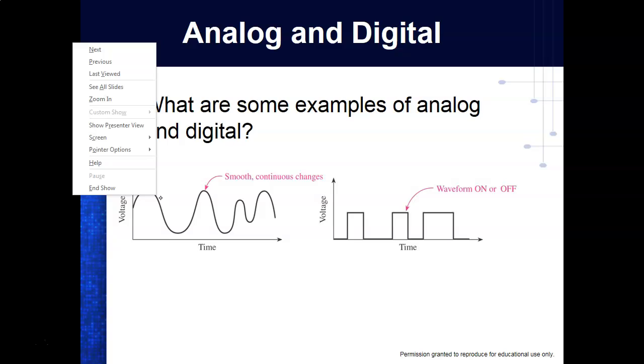So we got to set a resolution, and like I said, in PLC 2, we'll talk a little more about the analog inputs and how it actually works. But it runs from what we call an analog to digital converter, which converts it into a binary number with a weight that represents the weight of the analog input. And then we have what we call digital analog converters, which would take a binary number and convert it into a voltage or a current that represents that weight.